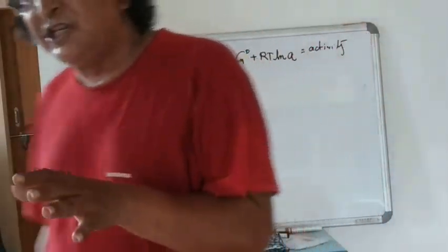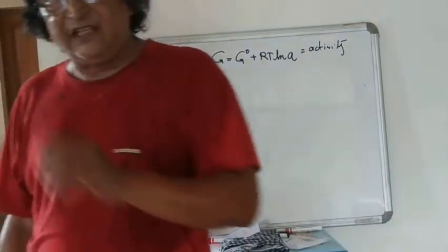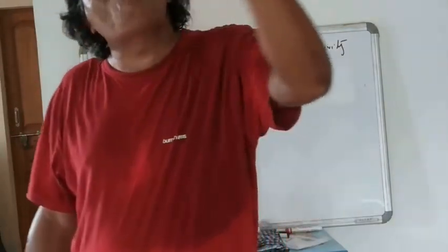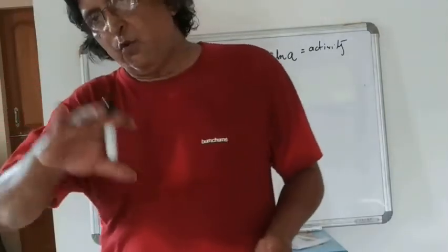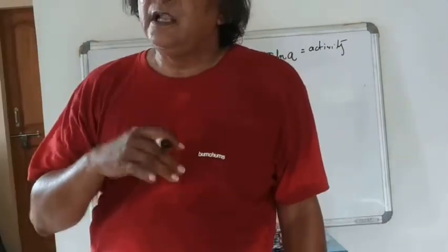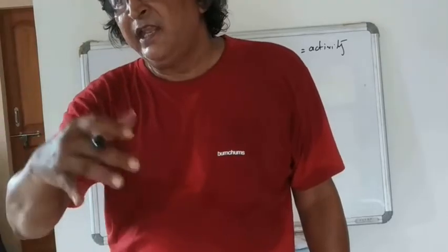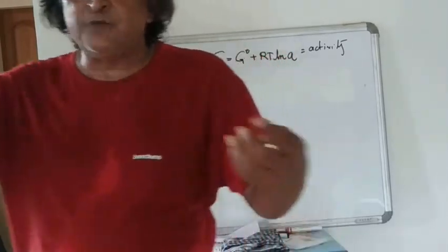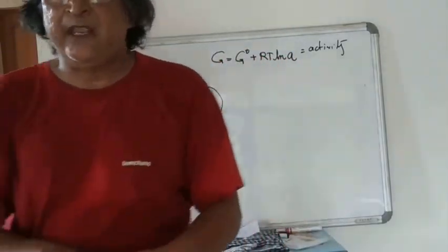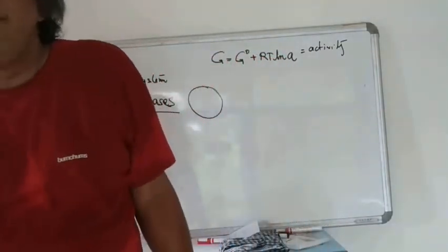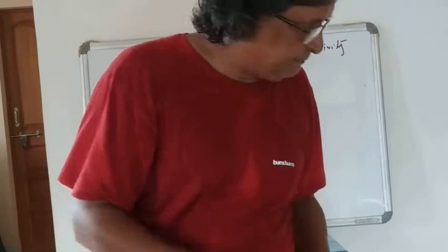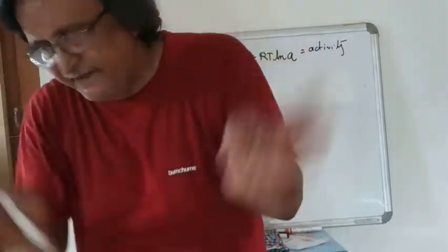Their compositions may be very different from the other phases, and they have defined boundaries by which you can separate one phase from the other. Say graphite and diamond, if both of them are there, it is not possible to have a diffuse boundary because their physical properties are different. You can't have any diffuse boundary between graphite and diamond. So they have definitive boundaries.